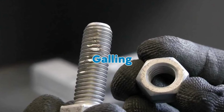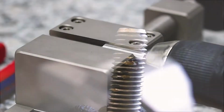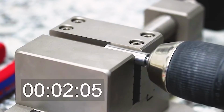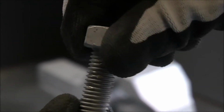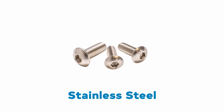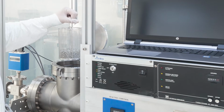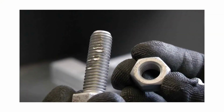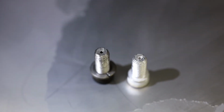6. Galling. Galling, often called cold welding or cold fusing, can occur when two fastener surfaces are placed under heavy pressure and locked together. Galling tends to be more common in alloys that self-generate an oxide surface film for corrosion protection, like stainless steel, aluminum, and titanium. In high vacuum and ultra-high vacuum systems, like materials can become cold fused together due to thermal expansion and the lack of moisture created by the vacuum.